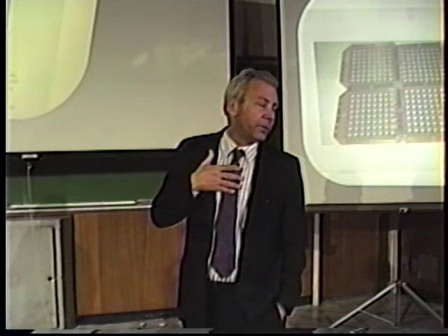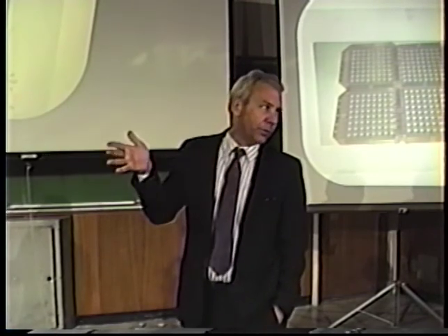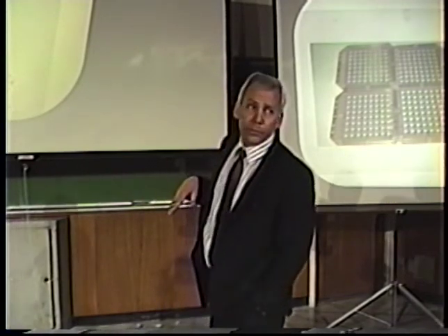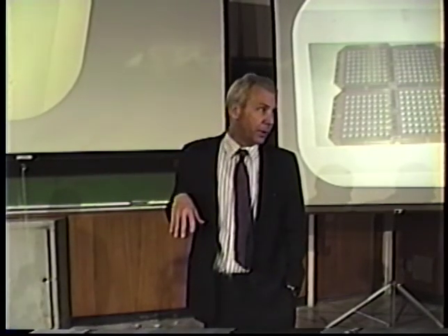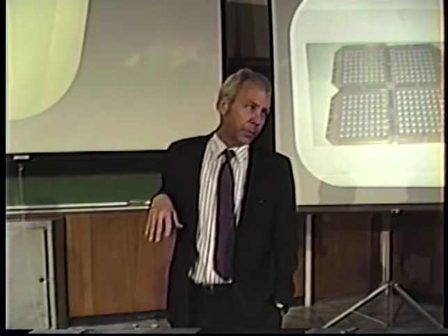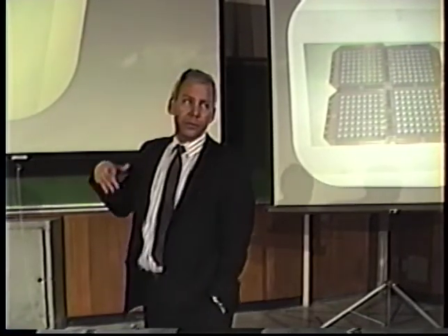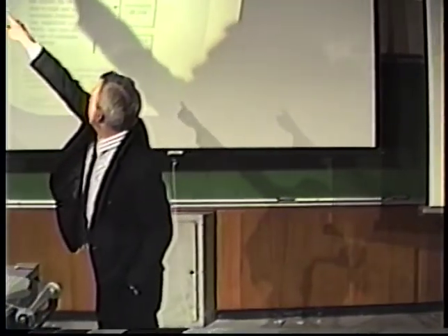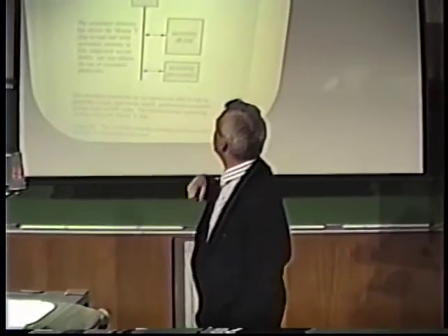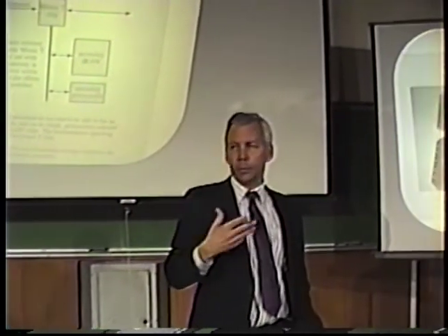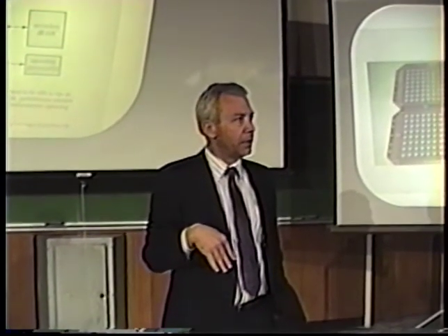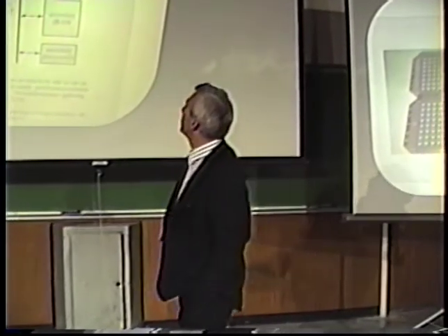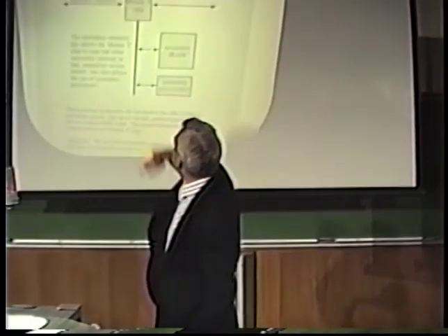Our existing 60 megabyte per second routers that we distribute to a lot of people are actually old technology. We have 200 megabyte per second routers. Indeed, the internal speed of our routers is more like 330 megabytes per second. It's just that it gets difficult to handle that on package pins. So this chip is built around a few basic numbers, 200 megabyte per second channels. If you want to be able to send and receive packets concurrently, you better have about 400 megabytes per second of memory bandwidth, which means that you need 2 banks.